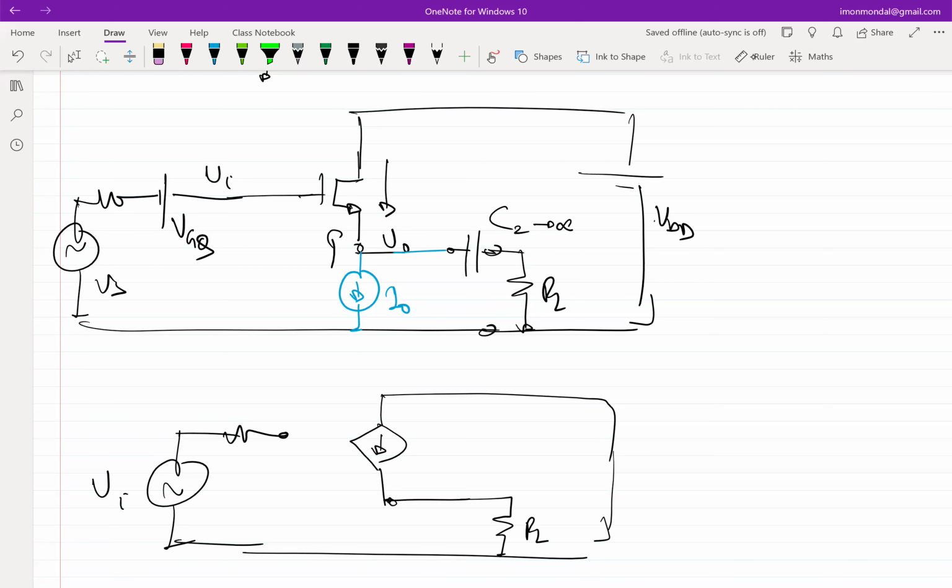You see that this architecture you have seen already, right? The way R naught is setting up the bias is an auto biasing mechanism. You apply a current source directly at the source of your transistor, and the source automatically adjusts itself, right?